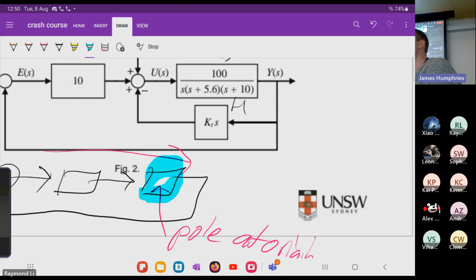Normally when we solve the problem, we put an integrator with a PID controller. That's in the forward path, and as a result, that will increase the type of the system. But if you put it down the bottom in the return path, that doesn't necessarily mean that, because it's not integrating the error. Does that make sense? Okay, hopefully that answers your question.